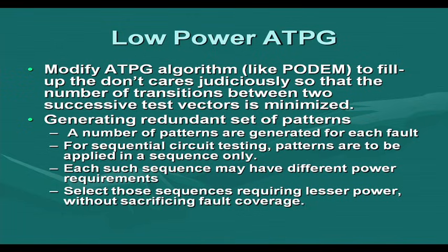So, any ATPG algorithm can have a post processing stage in which the don't care bits will be filled up judiciously, so that the number of transitions between two successive test vectors gets minimized. So, this is one possibility.